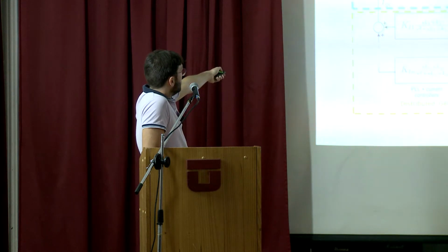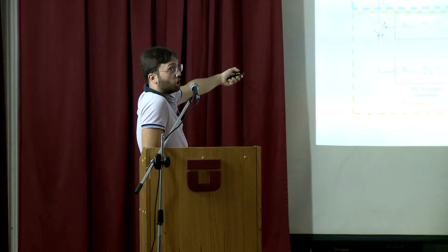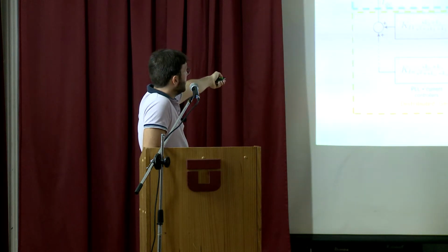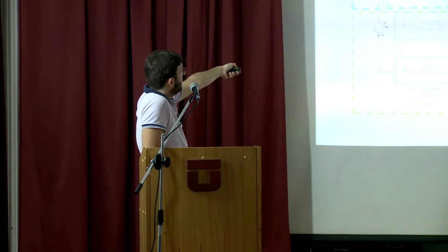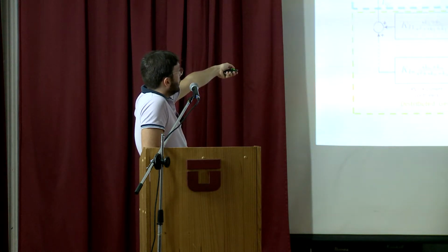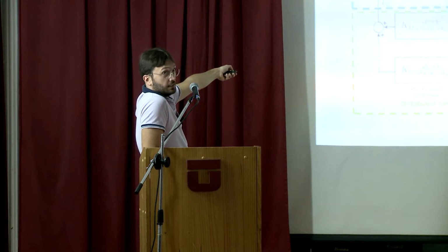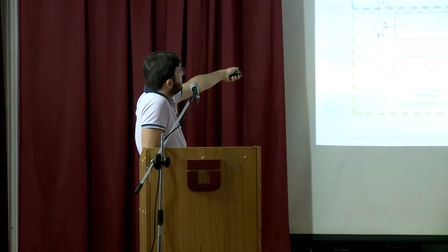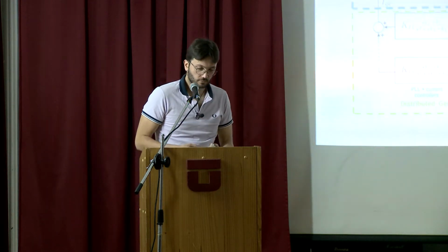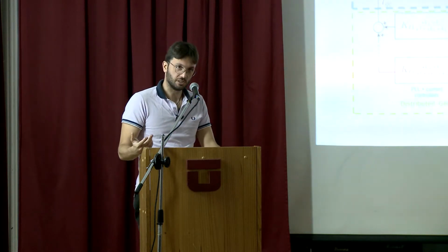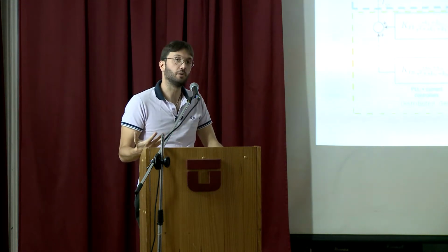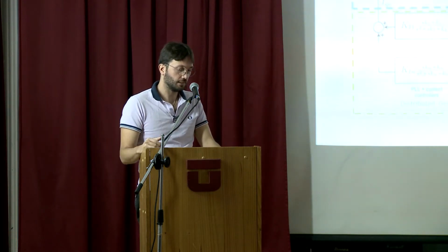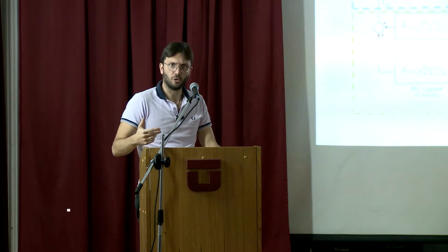Then the AC current that is flowing to the grid, okay, I have to remove some contribution of the load, but the integral of the current, because there is an S at the denominator, is basically the DC-link capacitor plus some coefficient. So I have many integrals in the system. I have the integral of the DC-link capacitor, the integral of the frequency, and the integral of the PLL. So we can already think that this system is going to be quite slow.